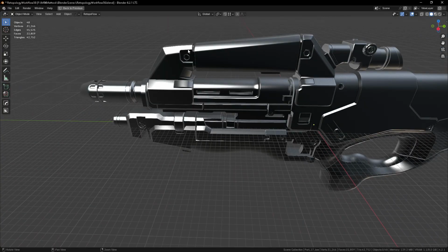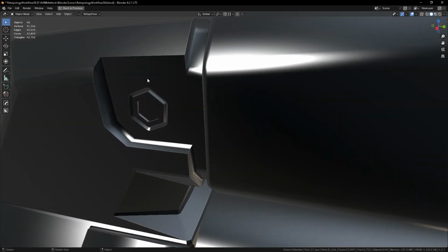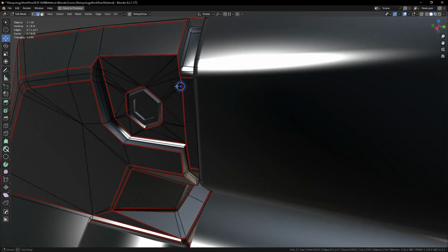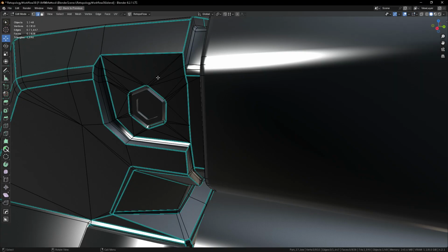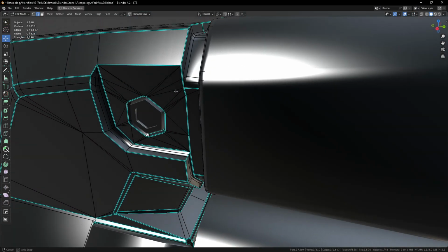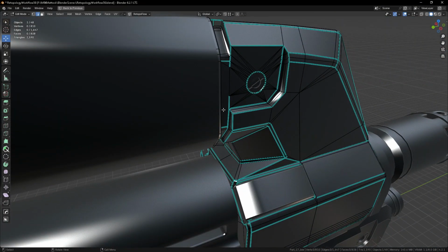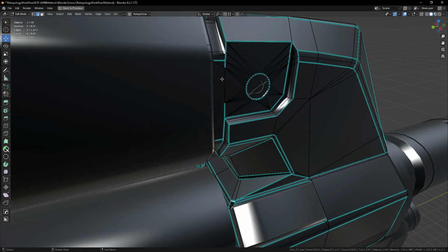So let's see what the problem might be right away here. Let me select this mesh, hit the tab key, and let me hide my scenes, and let's have a look at the hard edges. Oops. So this is more of an oversight, folks, than low texel density. Okay, that's why we saw that black line here.